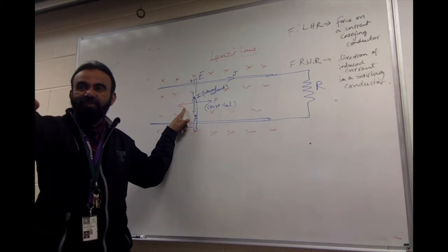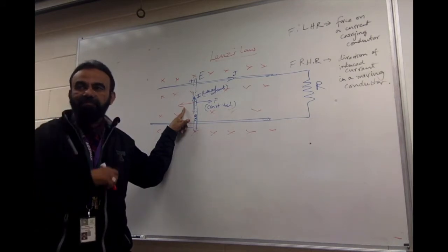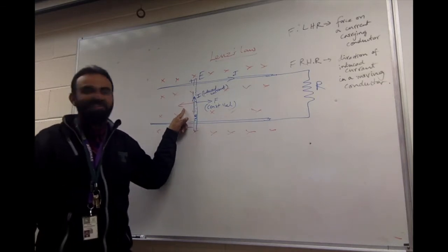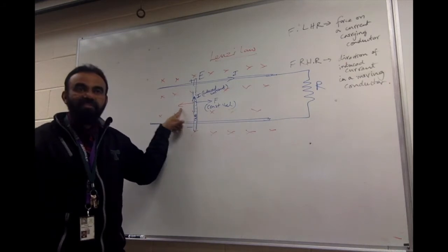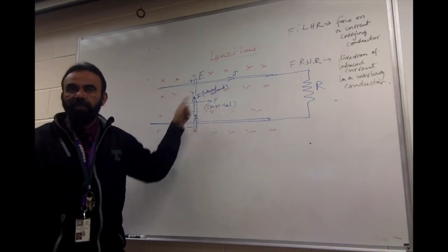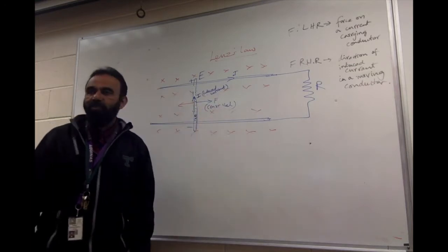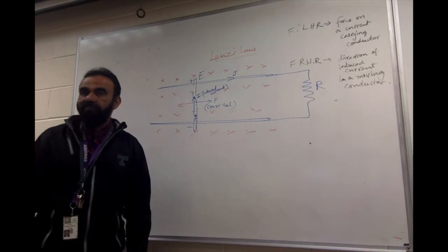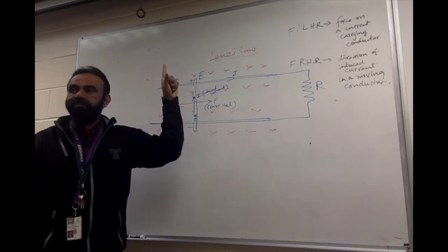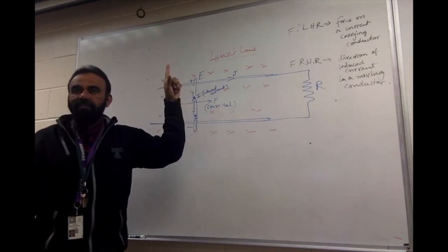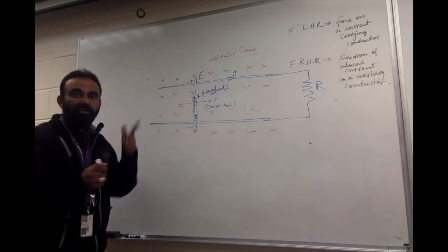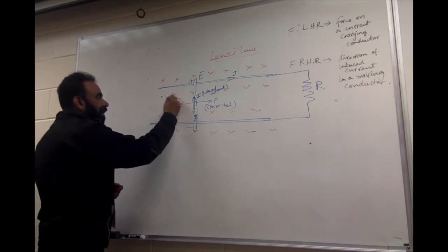And that is according to which law? Lenz's law. Look at that. This is a force of opposition that you are supposed to overcome. What's the net force here? Zero. So you are actually moving it with a constant velocity. Because if you try to push it harder here, this will also go up because the current will be higher now. You understand? So if you are pushing it with a certain force, you are going to fight this force, which according to Fleming's left-hand rule is BIL.